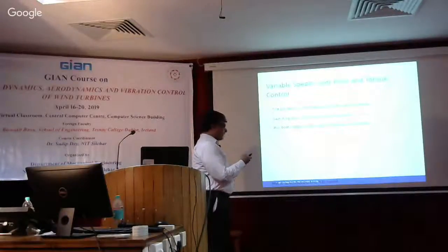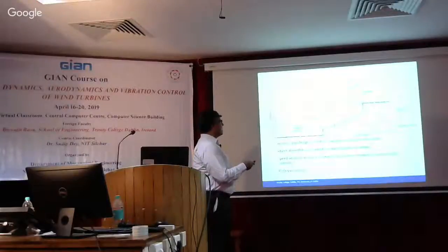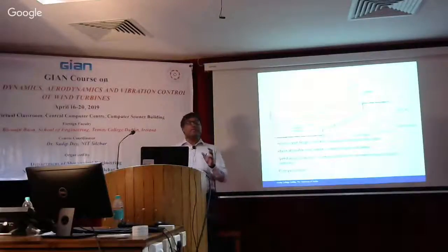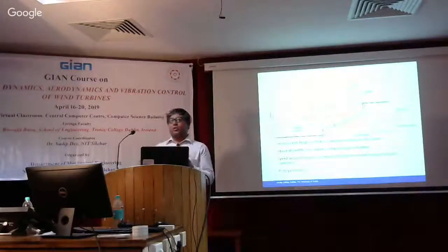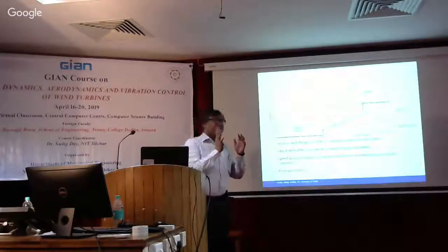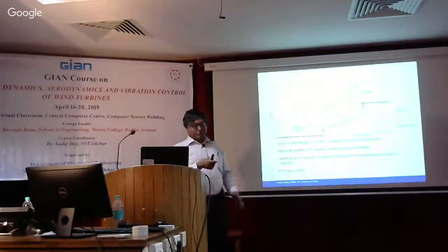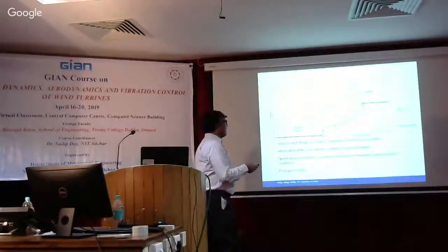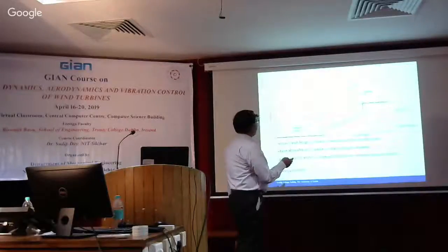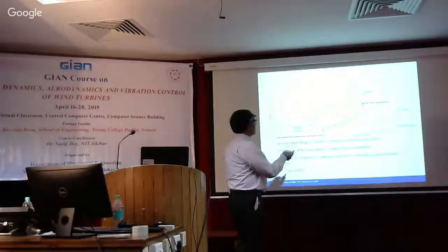The other thing I should have said is that the reason this is done is basically to decouple the torque and the pitch controller, because if you simultaneously use the torque and pitch controller, both will try to optimize, and then you will not have convergence. So it's better to fix one and then optimize the other. So in this case, for example, we are fixing the speed, and then based on the value of the torque, we are optimizing the power. So we are at a speed over here.